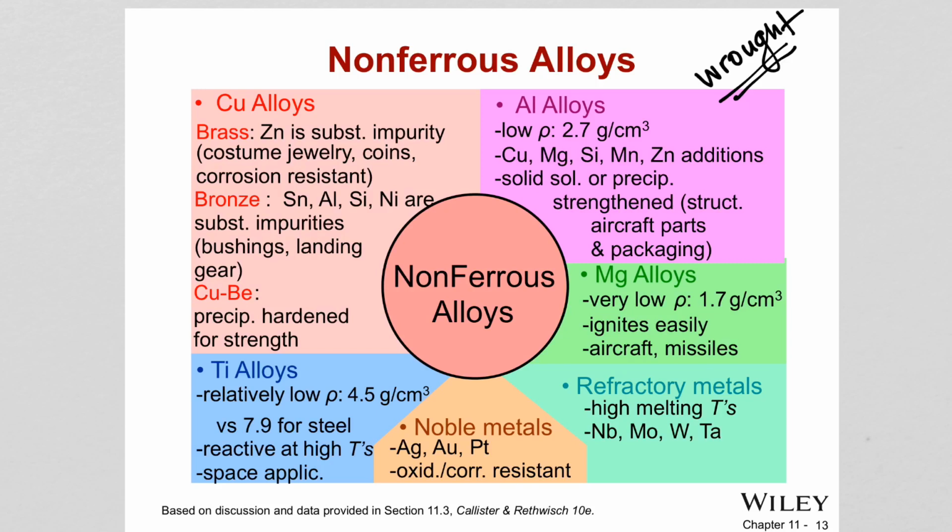But the very good thing about aluminum is that it can be strengthened, and this can be achieved by cold working and alloying. You can also do precipitation hardening, which is achieved by heat treatment. And please also make sure you watch the videos I'm sending you.